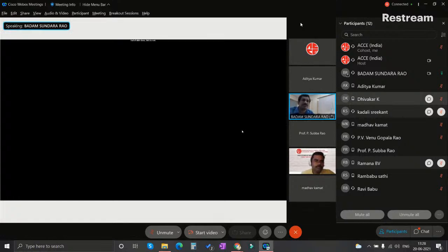The general classification is that the shaking intensity is not that much, which minimizes the liquefaction potential. In that matter, we can say so in a broad sense. Yeah, thank you, you are also coinciding with my opinion. For zone 3 also, we have to consider the liquefaction effect, because where the N values are very low, there is every possibility of liquefaction. So that aspect is to be considered, but no literature supports that for zone 3 you can neglect it.